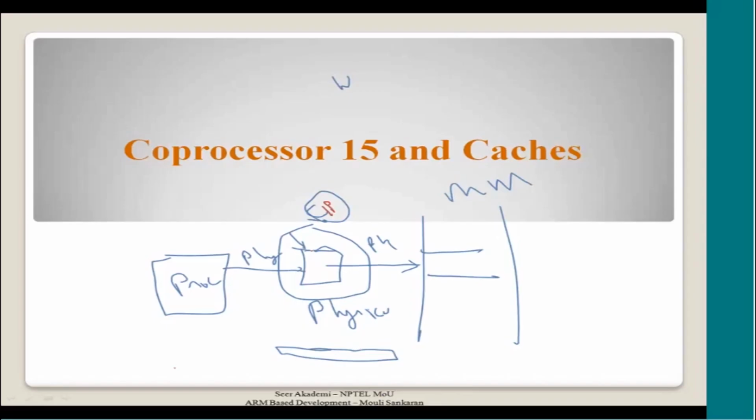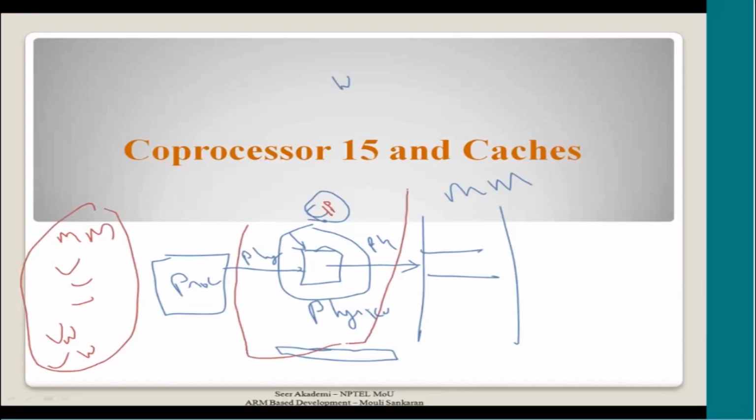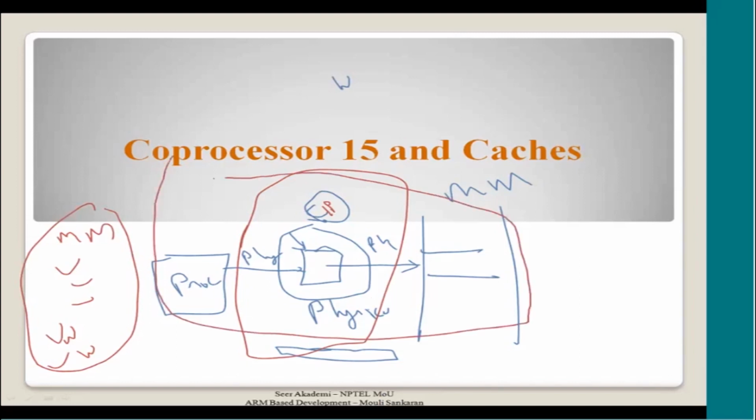That means you can choose a write-through policy or a write-back policy, or you can choose the memory mapping policy. Once you choose a particular set, it may remain the same throughout the execution of the program. You can even choose the IP and have only limited circuitry in the system so that your SoC is limited. That is fine, but sometimes you may want to give the configurability to the system programmer.